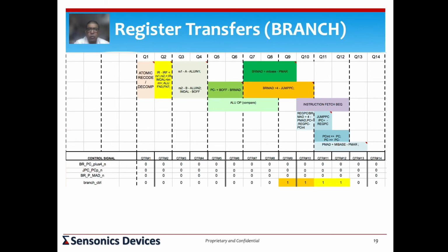There are other clever things that could happen, both in the case of branch as well as in the case of a jump, that the offset is 4 kilowords. So imagine that you had a cache on chip, and the RISC-V ISA tells you that it is expected that R1 or R5 will be used for the link register in case of subroutine calls. If you assume that it is being used and somebody has written a program that complies with this, then what you could potentially do, and they recommend that you can do it if you want to put in the hardware resources.